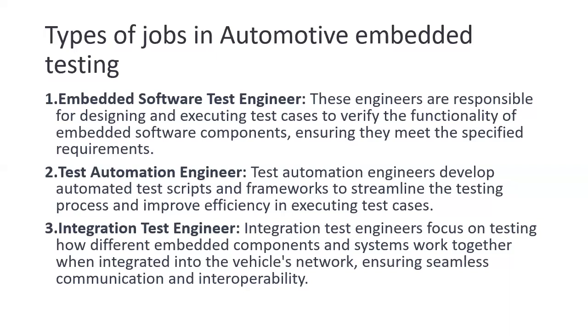But if you need to test the LEDs, LEDs meaning telltales, they call them telltales in the automotive domain. They need to be tested with automated test scripts, and an HTML report will be generated automatically. That type of job role is called a test automation engineer. After completion of manual testing in our project, we will teach you how telltales need to be automated using CAPL script. That CAPL test script we will teach you, and you need to execute some of the test scripts in your own way.